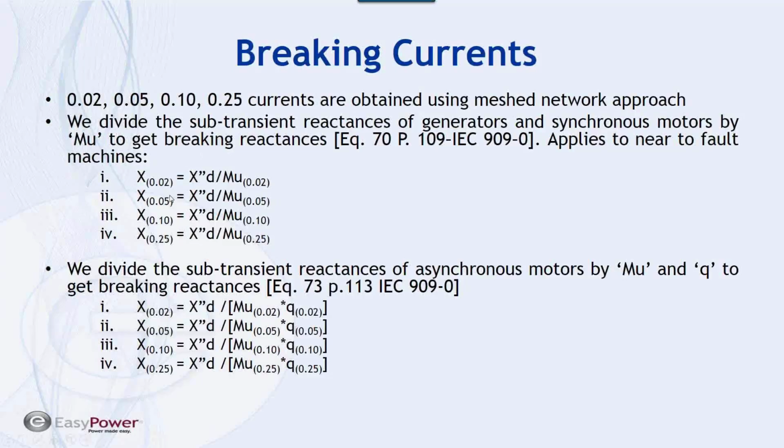For synchronous machines, so synchronous motors and generators, that's how we modify and adjust the impedance of the initial current. These values were the values that we use for initial currents. Then you would think that if there is a source which is supposed to have decay, the impedance has to go up. So you would look for a mechanism to increase the impedance value of those devices.